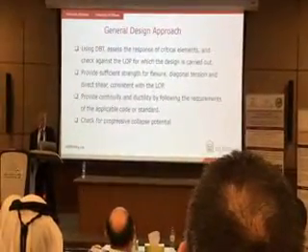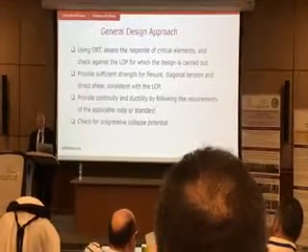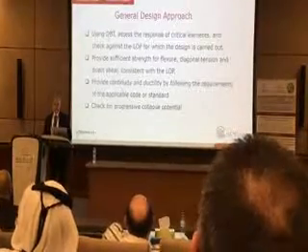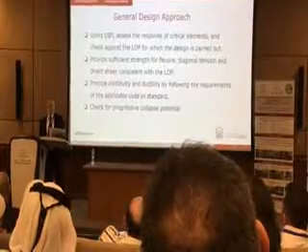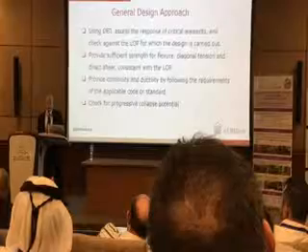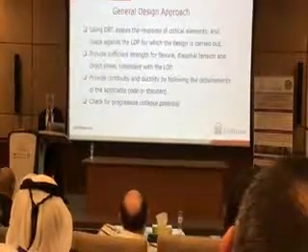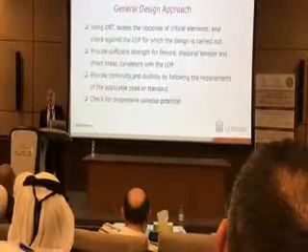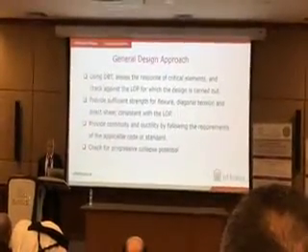Okay, so now we're approaching the end of this design presentation, and the general design approach involves you first come up with the design basis threat. This is the charge weight and stand-off distance, and you decide on the level of protection, or the building owner decides on the level of protection. You do your analysis to see what is the demand in terms of strength and ductility, and then you provide continuity and deformability to make sure that you meet those target levels.